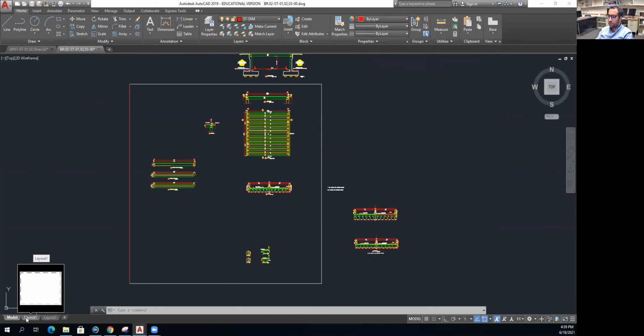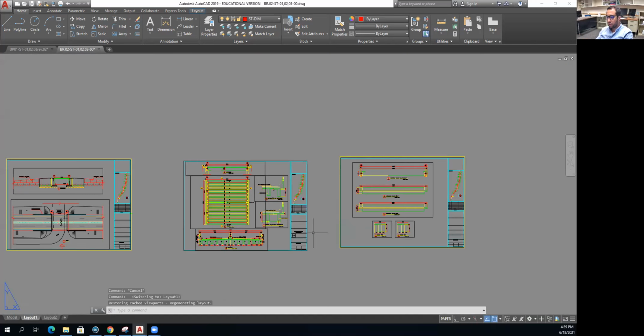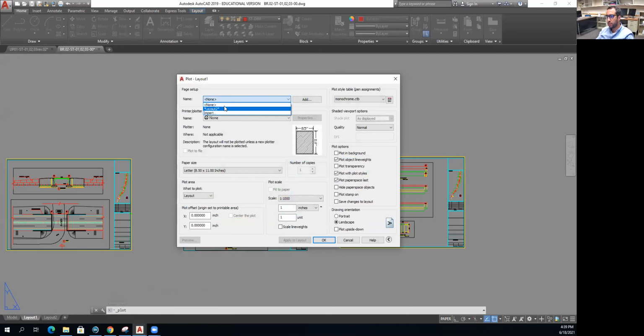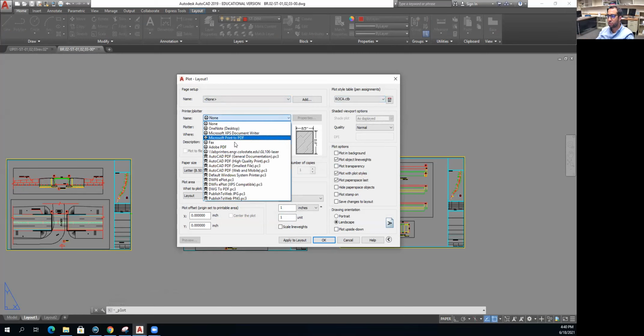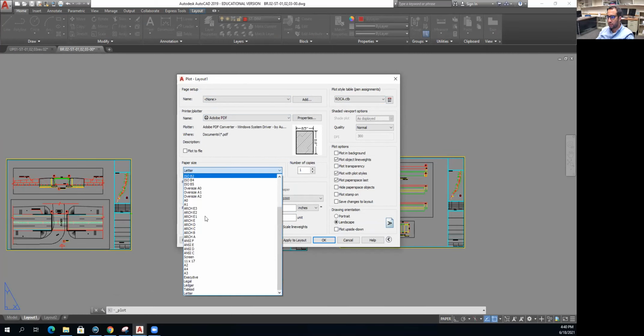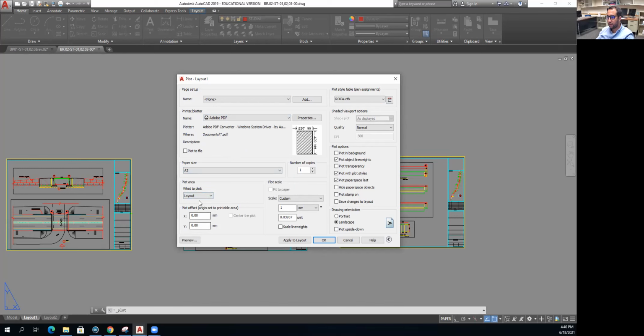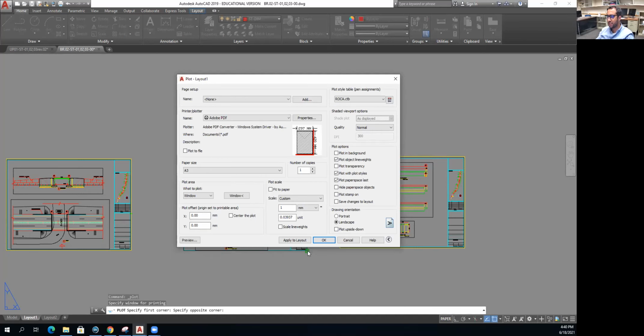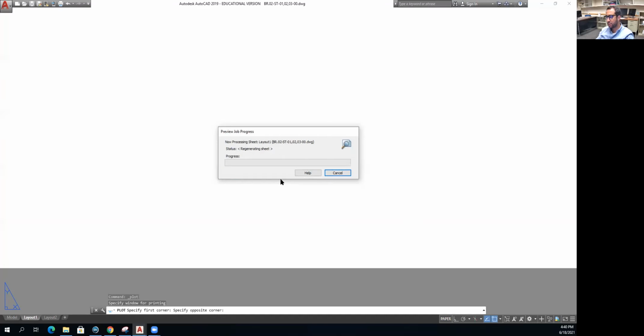Okay, and make sure that everything is drawn on a layer. Let me see if it's going to work over here. Okay, layout. I have my layers saved on something called Roca, and I want my drawing to be an A3, and then window to indicate the drawing that I want, and then my layout, my title box is in the same dimensions as an A3. Okay, so then let's see how it's going to look.